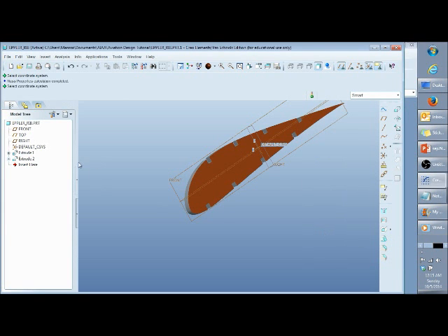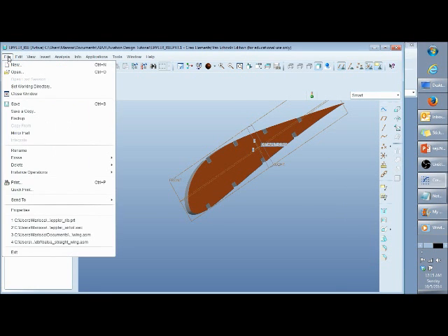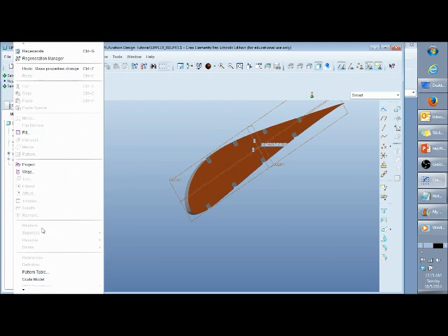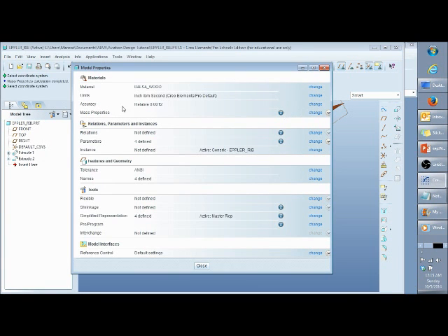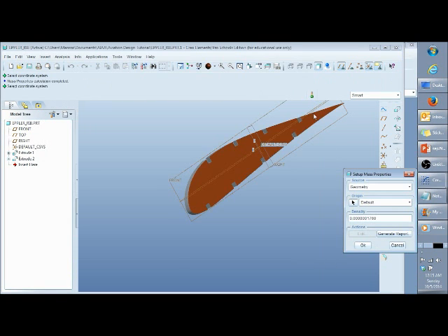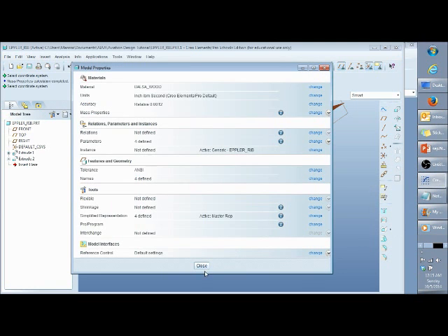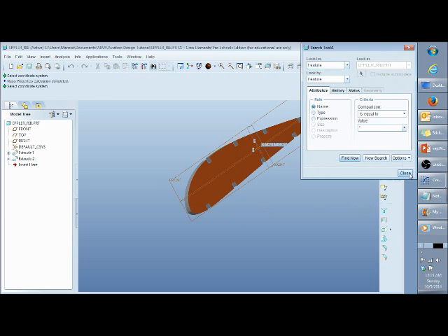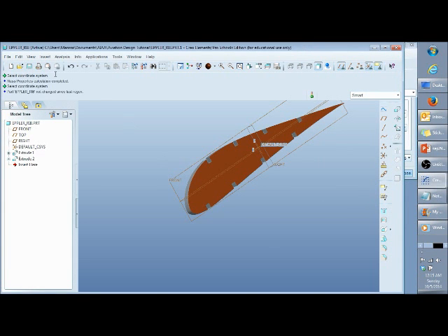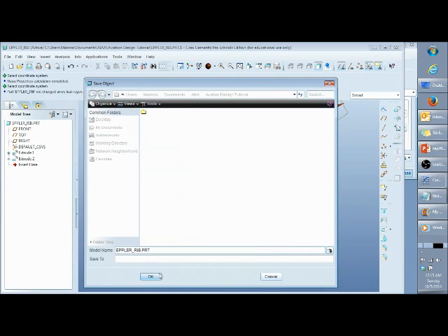Remember, if you need to manually enter and change your density because they don't have the material that you're looking for, if you're ever modeling a part, same thing. Just go to properties. Instead of going to the material, go to mass properties and change it. Manually enter and change your density right here. Hit OK. It should update to whatever the density is changed to. Control G. Control S. Save it.